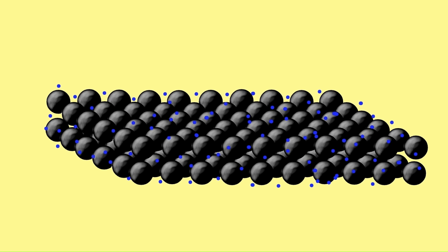We also know semiconductors tend to lose electrons easily after absorbing thermal or optical energy. For easier understanding, I have shown atoms spread linearly in a very regular manner. However, one s orbital and 3 p orbitals of the silicon atom hybridize together to form sp3 hybridized orbitals, resulting in a tetrahedral shape. And if we talk about the crystal structure, then silicon, germanium and a few other semiconductors are usually found in diamond structure.